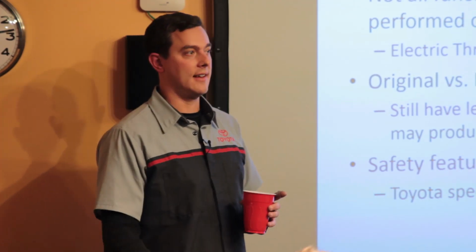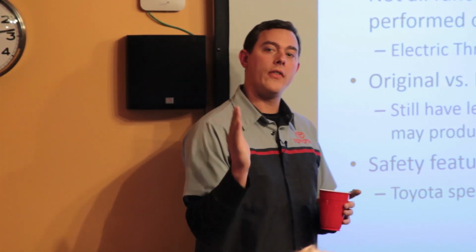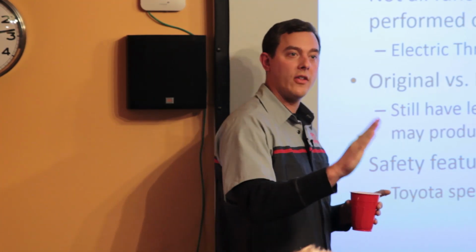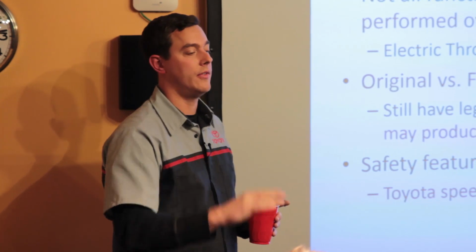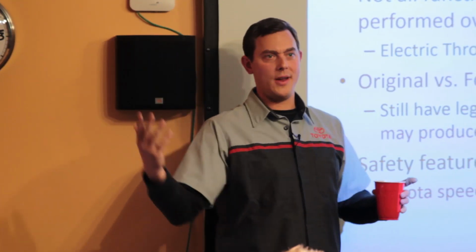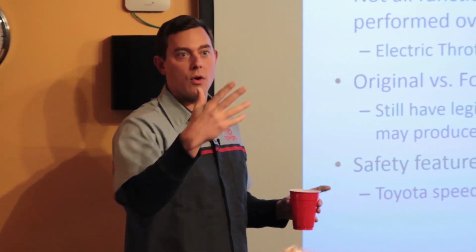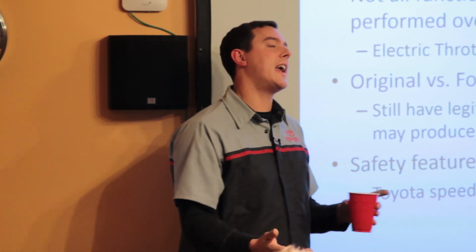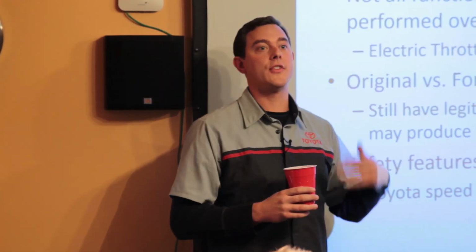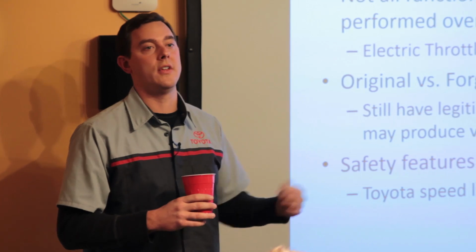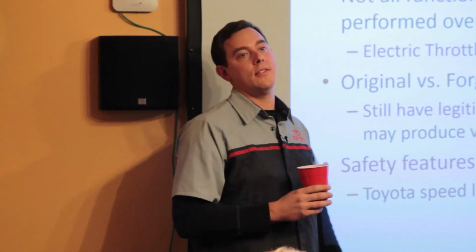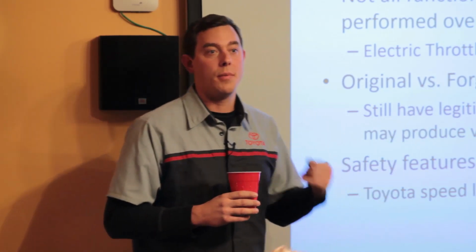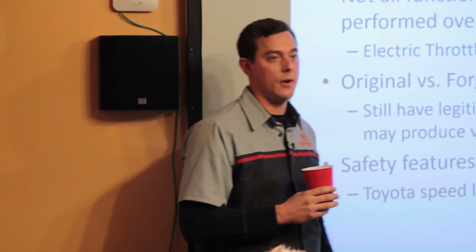You'll even see things like, on the CAN network, the angle of the accelerator pedal. You could see it go higher to lower as you depressed it and released it. And I was like, sweet, put it to high, I'll play that on the network, and the car will zoom forward, right? It's not the case. There are reporters, sensors just telling you what's up, and there are consumers of that information. If there's really no consumer of that information, then it doesn't really mean anything. I'm sure there's something that's messed up in the car, but it didn't physically control the automobile.